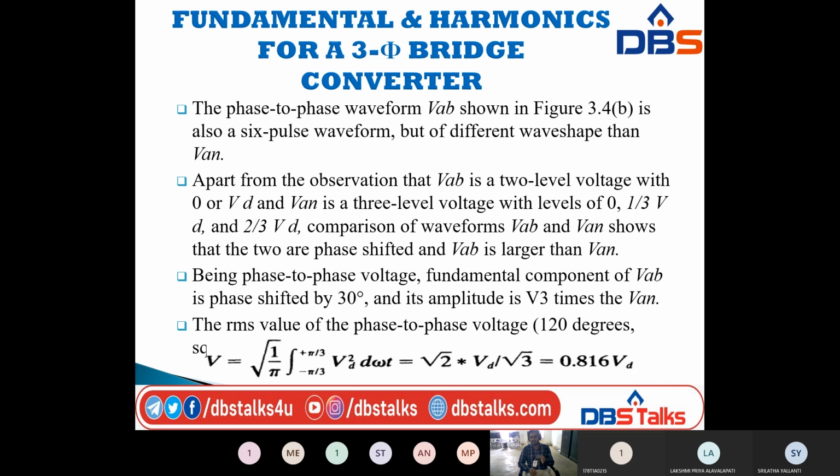Apart from the observation that VAB is a 2-level voltage, containing the values 0 or Vd, VAN is a 3-level voltage, that is 0, 1 by 3 Vd and 2 by 3 Vd.